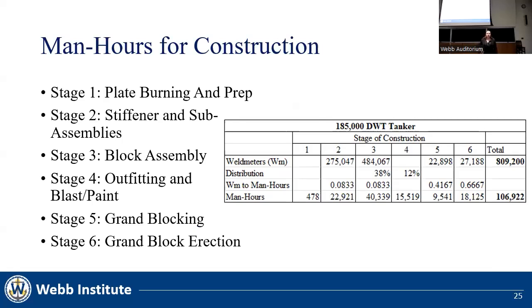The large tanker block breakdown contained weld information for stages 2, 3, 5, and 6. Therefore, the man hours were directly calculated using a factor of roughly 5 minutes to weld 1 meter with setup included. This number was given to me by a weld engineer from Philly Shipyard. This factor was then multiplied by 5 in stage 5 and 8 in stage 6 to follow the 1-5-8 rule discussed by Ian Bush, who explains that it takes longer to weld the same distance the further the ship is in construction.